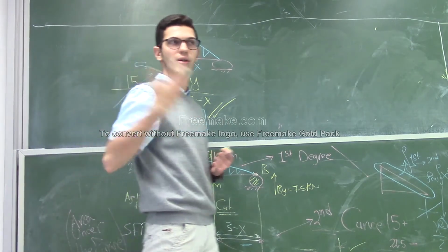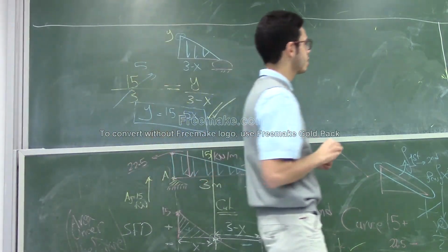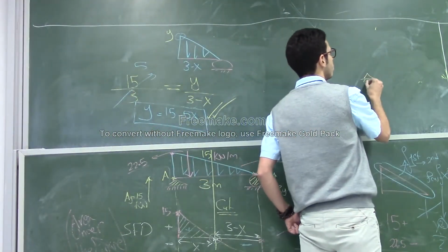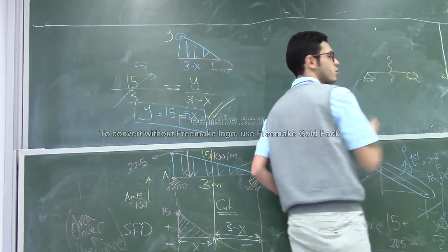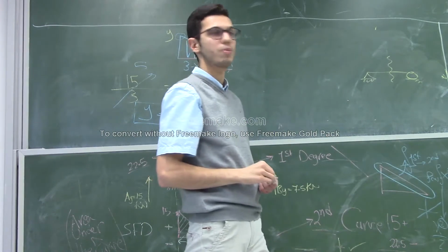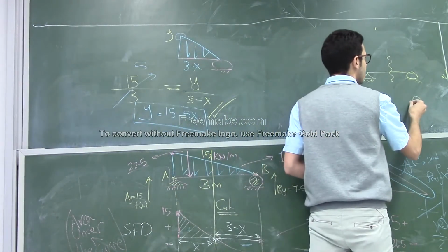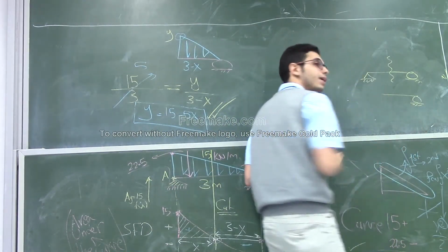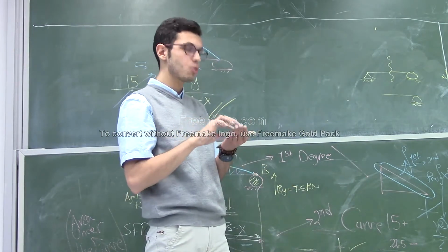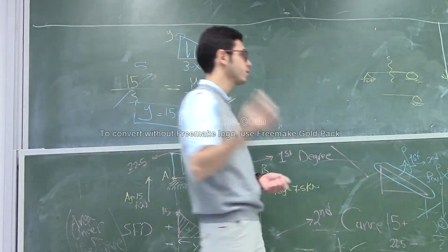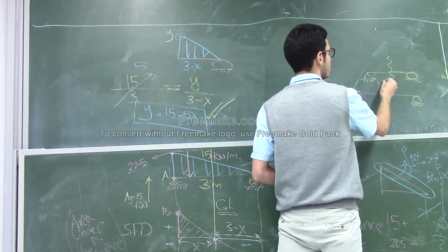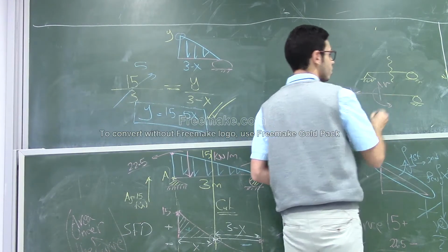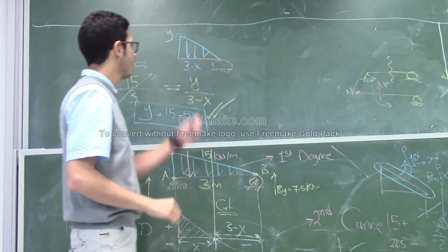In the first lecture, last week, I said that if you have a beam and you make any cut through this beam, when you make this cut, three reactions will appear: normal force, shear force, and moment.